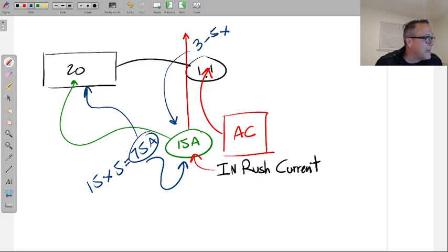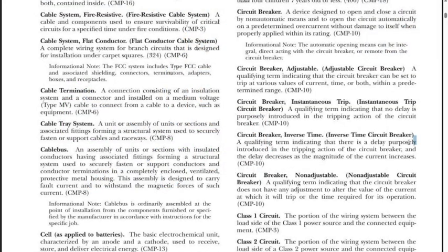That's why this breaker has a delay feature. And that's why all of the general breakers that we put have this little delay feature. So that in the event when things first turn on, and you get this spike of energy, sometimes it's called the spike of energy. You can more so understand it because you guys are electricians as a spike of amperage. Then that breaker doesn't trip. Right? That's where it's featured at. A delay purposely introduced in the tripping action.